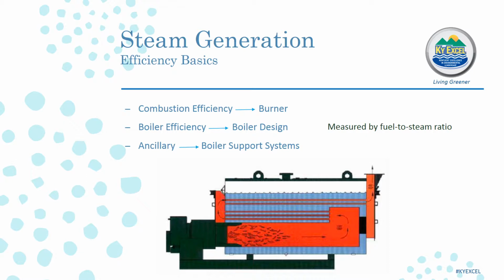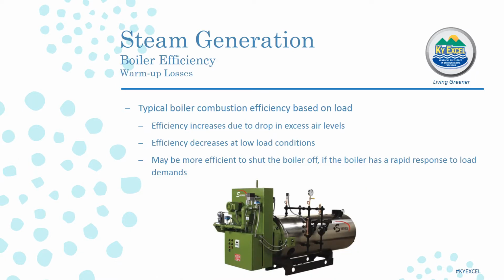It is common for stated boiler efficiency to be less than combustion efficiency. It is a general observation that boiler efficiency tends to decrease as the boiler load decreases. Both practically and theoretically for any boiler, the efficiency is highest at maximum load conditions. At part loads, a considerable drop in efficiency is noticed.